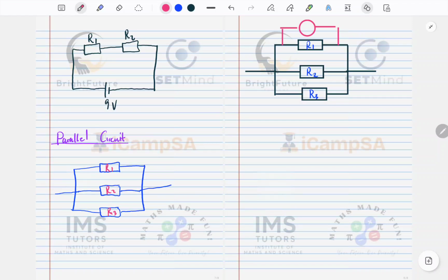So let's just assume this is all connected like this, because these are wires. So this is V. You can see that this voltage here is gonna be measured even if I put another here and put another here. So how this thing would be, let me write it here as the rules. We're gonna have VT, which might be our source, equals V1 equals V2 equals V3.